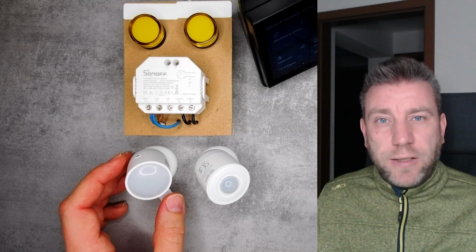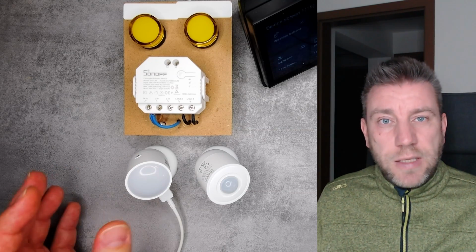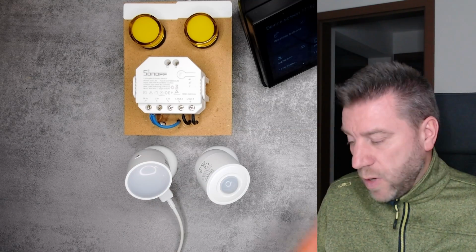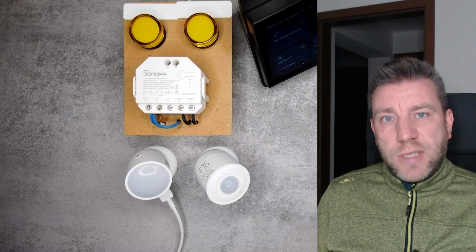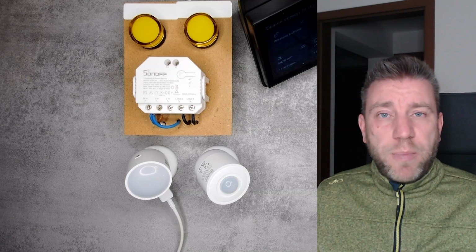That's a presence sensor, which works on a different technology, and it's much better at detecting presence, as in somebody being in a room, whereas the PIR sensor is much better at detecting bigger motions as you walk into the room. But if you stay in the room and you are relatively motionless, or you're just sitting in a chair reading or watching TV, it's not going to detect your presence, because that's not really motion anymore. I've covered this in a separate video, where I compared how the two behave and how they work. So again, you can check that video out.